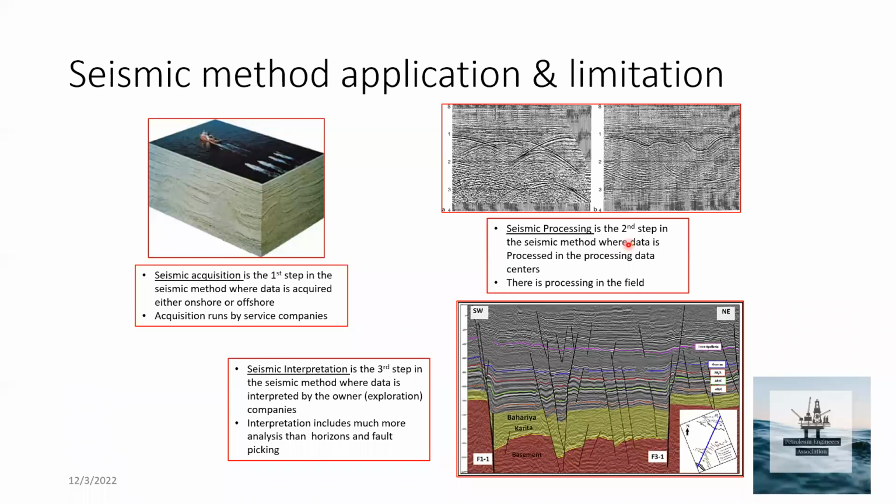So the seismic method application is divided into three main parts, as most of us know. Seismic acquisition, which is the step of acquiring the data. Seismic processing, which is filtering the data, removing the multiples, adjusting the velocity, doing the migration. Seismic interpretation is the third and final step,